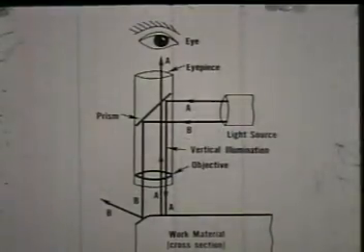The presence of the dark band is easy to explain. When the light from a metallurgical microscope, such as A in the sketch, strikes a smooth perpendicular surface, it is reflected up through the eyepiece and the surface appears white to the eye. However, a beam of light such as B that strikes an inclined surface is reflected outside the microscope, and that surface appears black and is unseen.